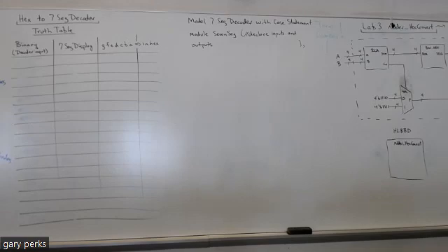So putting the NOT gate there, which again is just this thing called a transistor. You're going to learn all about transistors in your first three. Well, are you EE or CPE? Yeah, EEs take a trilogy of semiconductor classes like 306, 307, 308. 306 is when you learn the basics of diodes and transistors. When you take that class, you learn that there's two basic uses of a transistor. One is a switch, an electronic switch. The other is an amplifier. But even when you use a transistor as a switch, you can still get current gain from it. Now, you won't get the optimum like you will when you use it as an amplifier, but you can still get some current gain.